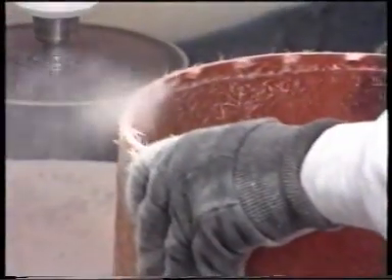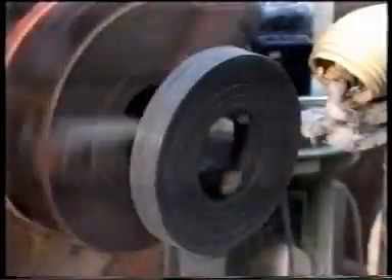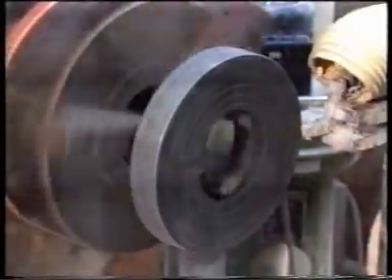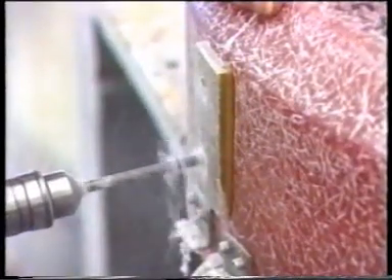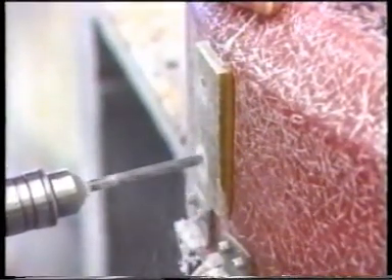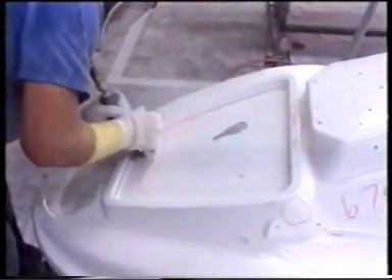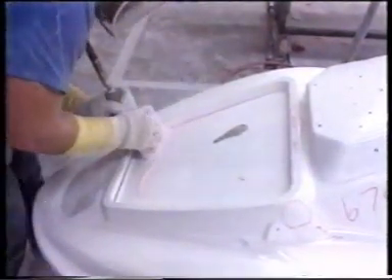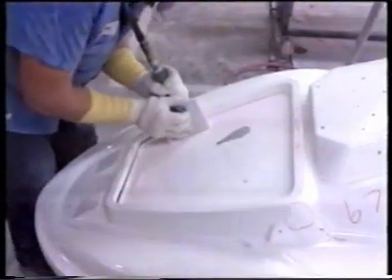After curing, polymer matrix composites can be cut, machined, drilled, and otherwise fabricated by many of the same methods used for metals. However, because the materials are abrasive and brittle, the need to maintain sharp tools to prevent delamination cannot be overstressed.